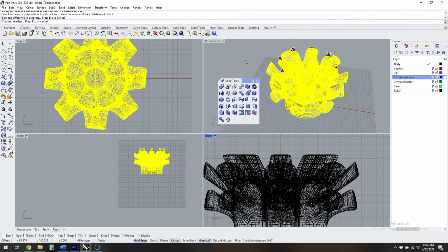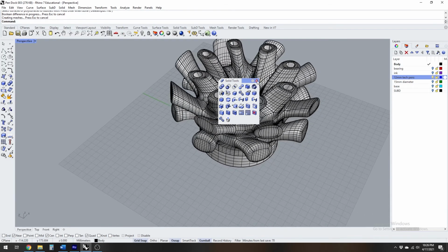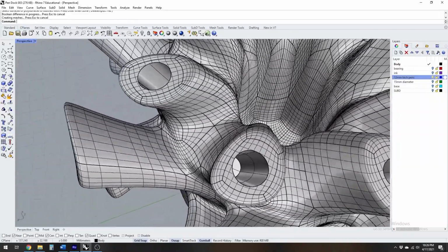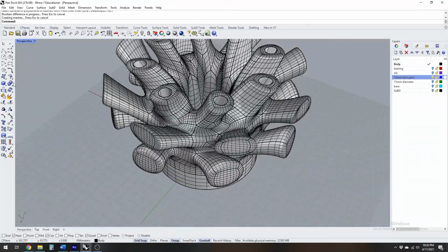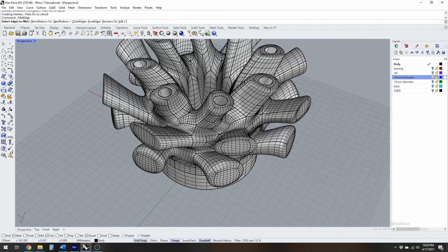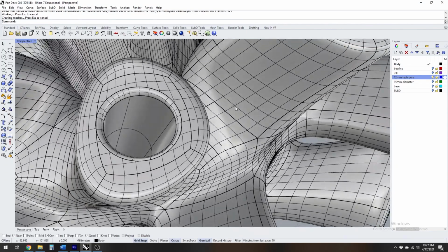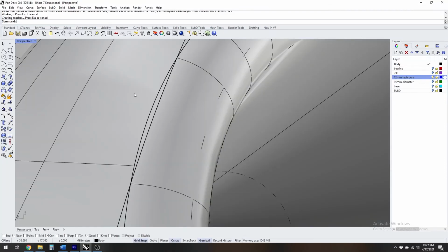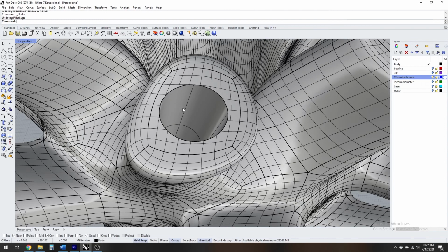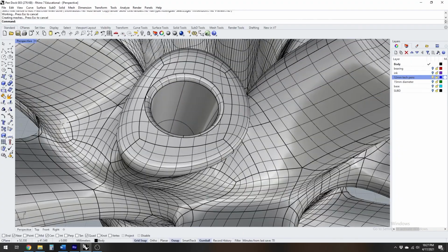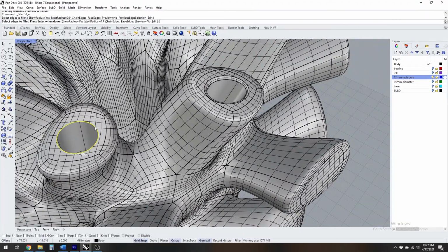Let's be honest. You're supposed to make multiple prototypes and multiple changes, but usually you wait till the end of the process to develop the 3D model, and then it takes a week to do the model and the print, and by the time you get that back, you may have a chance to do one. Now here you're seeing me actually run a fillet command. This fillet was a little bit big, and it started to eke into that little isoparm over there, so I think I'll tone this down just a little bit. I don't want to push it too much, but I will look into how we can manage those relationships. Considering those lines fall on the faces, I do have control over that in the future.